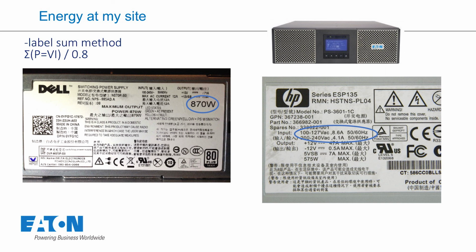So that's for you to know how to easily calculate how much energy each rack consumes. If you calculate one rack, you do it individually for each rack, and you calculate the power consumption on the row itself if you're doing power distribution at the row level of racks, instead of individually for each rack. So that's something to keep in mind.